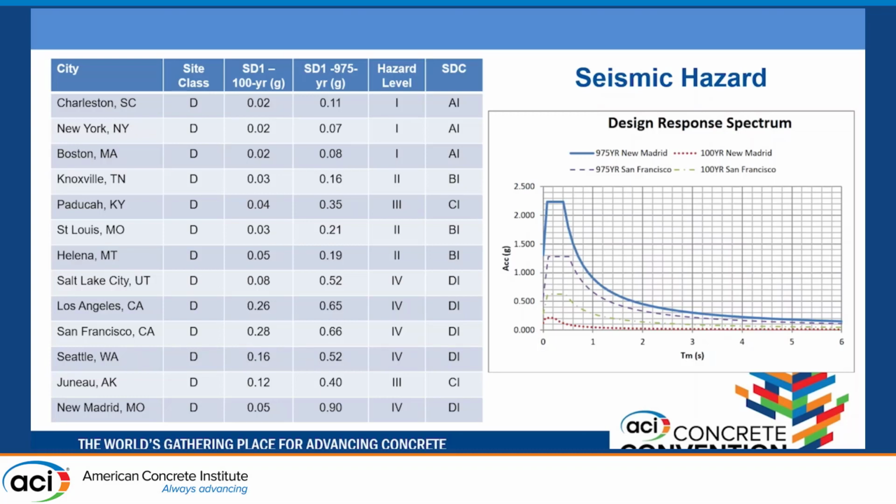So the 975 was determined many years ago with AASHTO, where historically we've been designing for 500 years. We knew that there were parts of the country where the earthquake hazard for 500 years was very much less than what some of these sites could see, say in New Madrid, or Charleston, South Carolina. So there was, at one point, an NCHRP project where we proposed 2,500 years as the design, and that was thought to be too big. This kind of became a judgment call.